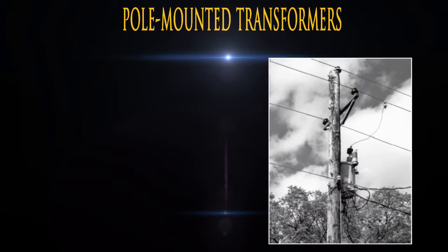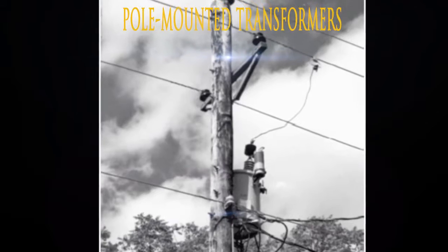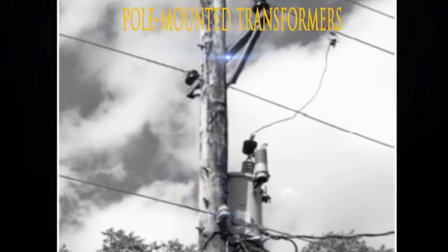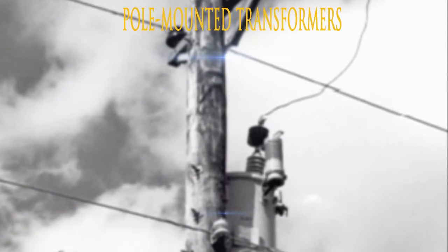A partial range current limiting fuse is mounted on the primary bushing, connecting it in series with a high voltage winding to prevent a violent failure of the transformer if an internal fault develops.